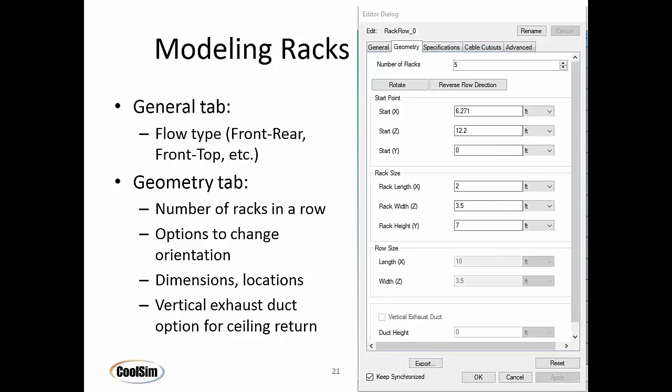Specifically, the dimension of a rack doesn't really have that big an influence on the simulation itself within a certain range. In other words, the difference between a 42U rack and a 48U rack is fairly insignificant. It's the heat load that we're worried about. And so assuming that your racks are the same size, unless they're off by a foot or two or 6 inches or so, is a fairly good assumption.